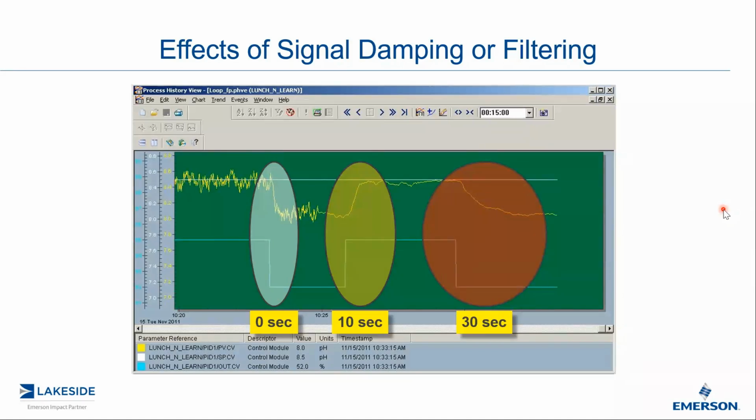You can just see the piping person, the process person, say, what kind of gap do you need for your mag meter? And you answer the phone, you say, well, I probably need maybe 33 centimeter gap, and that way I can put it in there. And then lo and behold, you walk up there with your mag meter, and you see your gap, it is flanged right to the elbow, and therefore that's where you've got to put it in.